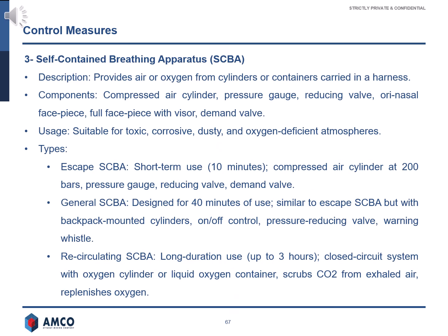3. Self-contained breathing apparatus, SCBA. Description: provides air or oxygen from cylinders or containers carried in a harness. Components: compressed air cylinder, pressure gauge, reducing valve, orinasal facepiece, full facepiece with visor, demand valve. Usage: suitable for toxic, corrosive, dusty, and oxygen-deficient atmospheres.